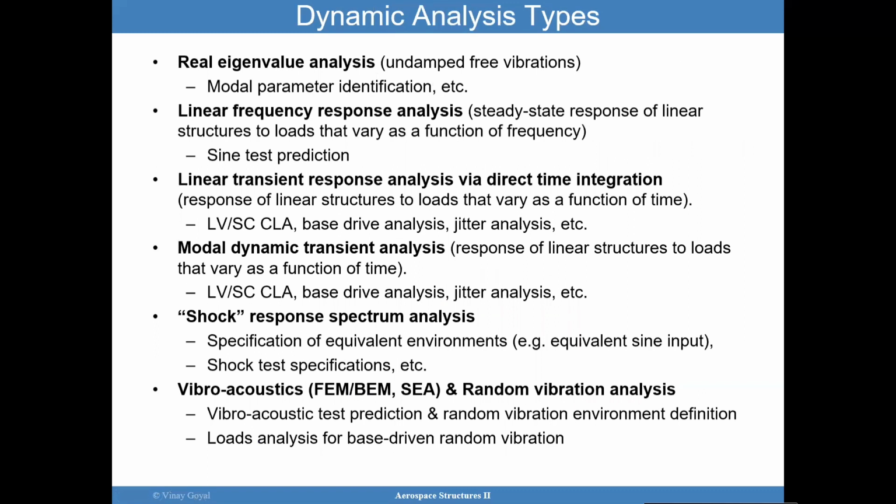What are the different types of dynamic analyses that could be conducted? You have the real eigenvalue analyses. This is basically a free vibrations problem, meaning I have that plate that I showed you earlier, and that plate is plucked. So what are those natural frequencies and mode shapes that that plate is going to take?